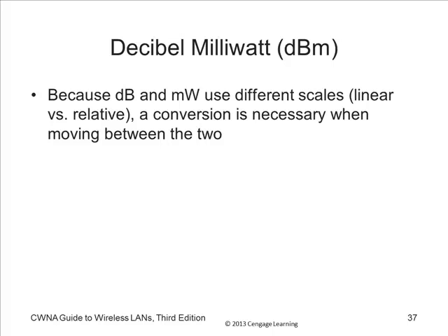And when you look at these things, you're going to get something like minus 50 dBm or minus 80 dBm. If you get minus 80 dBm, you're probably not going very far. You don't have a very strong signal. And as you get a decrease in the signal strength, the data rate goes down. So if you get a minus 80 dBm on your 54 megabit per second wireless access point, you may be getting 2 megabits per second.